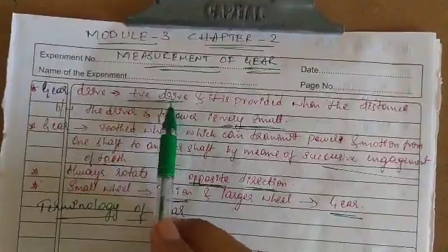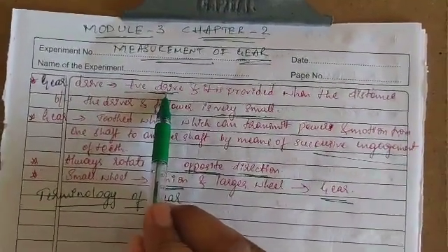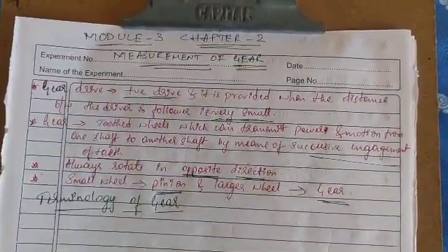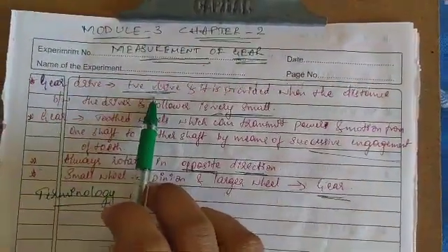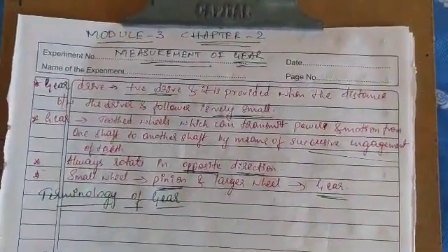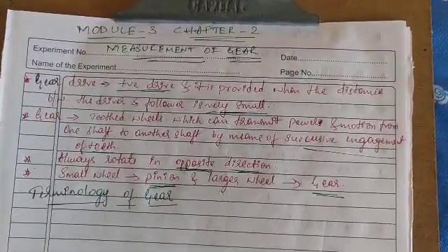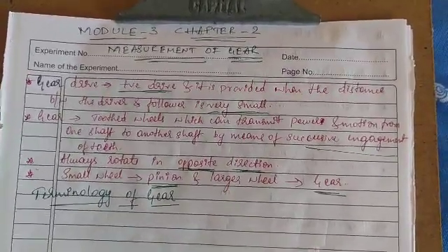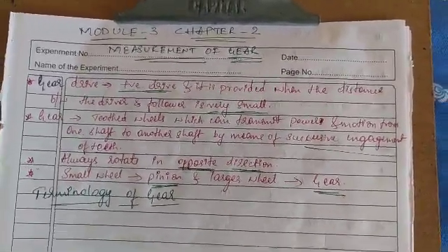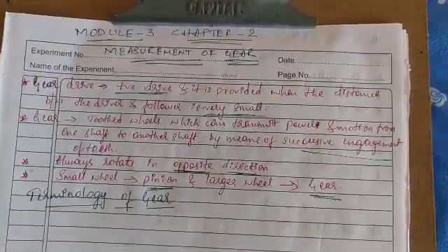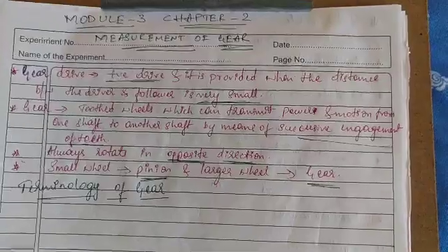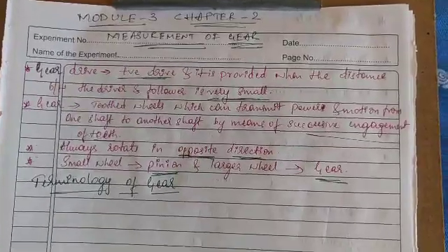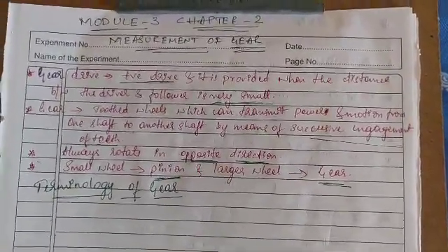Basically the gear drive, already we know that it is a positive drive because no slipping takes place in the gear drives, so we can call it a positive drive. It transmits an exact velocity ratio, it can transmit large power with a low velocity, and it has high efficiency and is reliable also. It can be used to transmit power between two shafts which are parallel, intersecting, or non-parallel and non-intersecting. And it can be used for changing the speed ratio over a wide range. Because of these advantages, we are using gear drives.